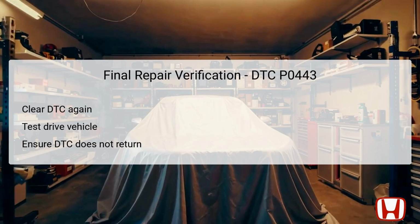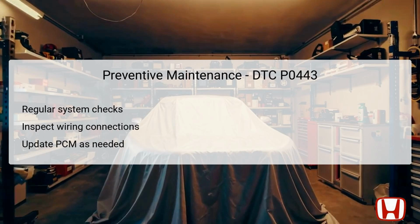After the test drive, reconnect the HDS to scan for any returning DTCs. If DTC P0443 does not reappear, it signifies that the repair process was successful and the EVAP system is operating correctly. Performing this verification step is critical to ensure that no leftovers from previous issues affect the vehicle's performance or emissions compliance. Preventive maintenance is crucial to avoid future occurrences of DTC P0443 and ensures the longevity of the vehicle's